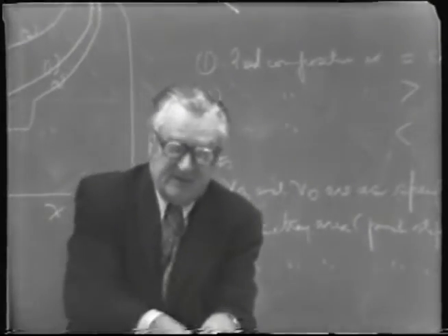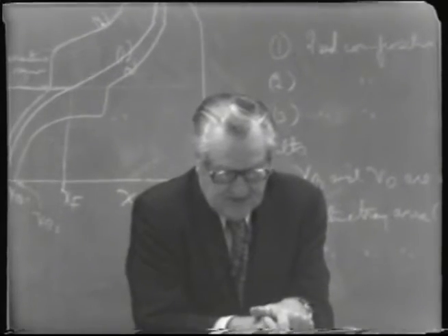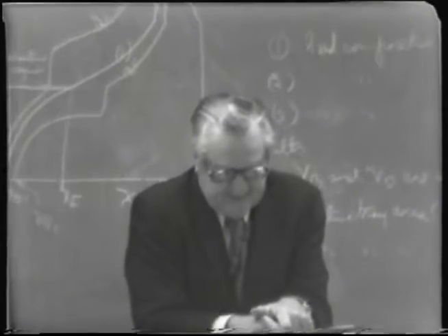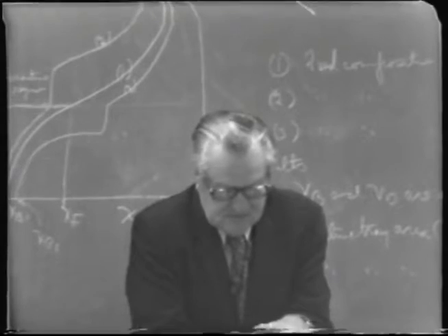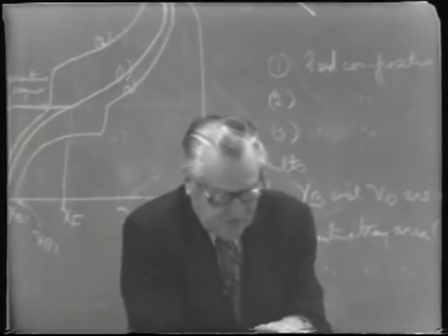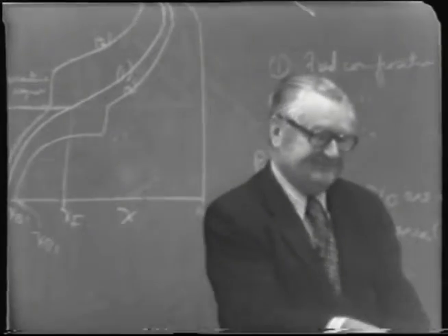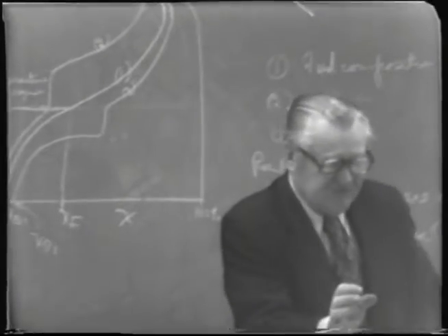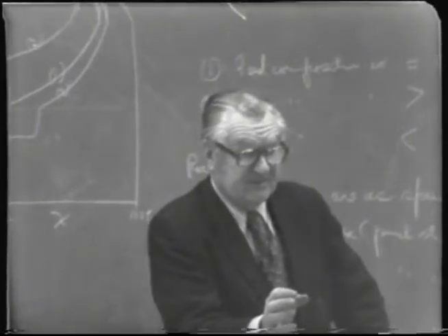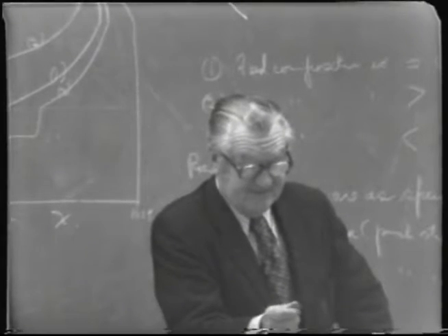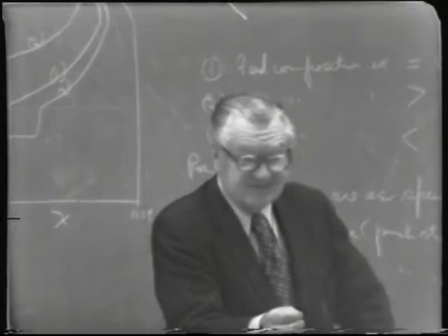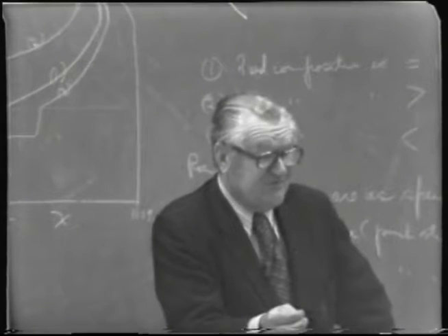And another point in connection with this is that many of the stripping sections that are used in California are not highly efficient, in the sense that they're sieve trays and they're operated in such a way, with a very high load rate, that they probably only get a plate efficiency of 40% or something like that, 40 or 50%.